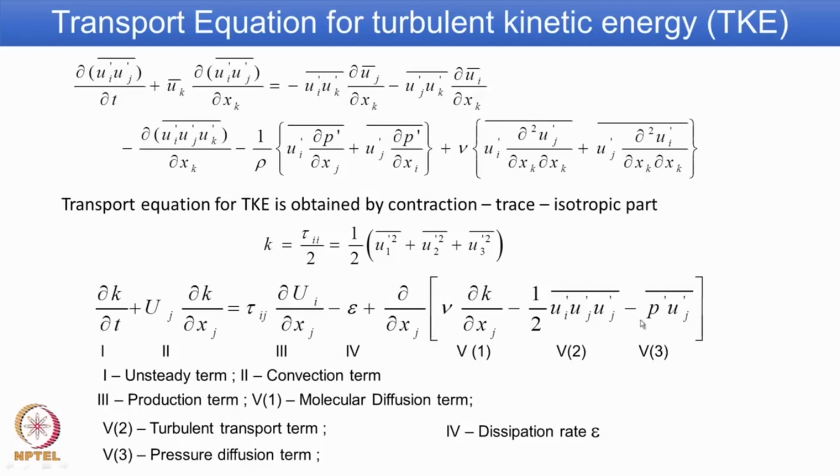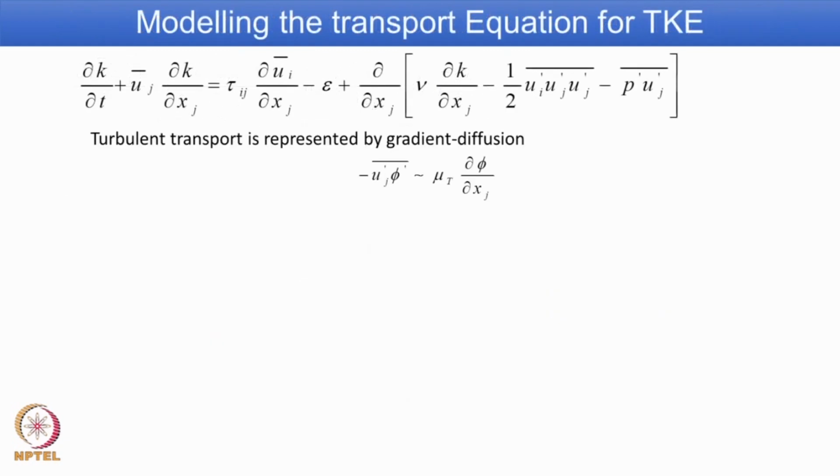Now, in this equation, we have to replace the second term and third term and try to combine them along with the first term using the defined quantity for k-epsilon or using the Boussinesq eddy viscosity concept, and that is modeling. We have done all this. Now, we look at the details.